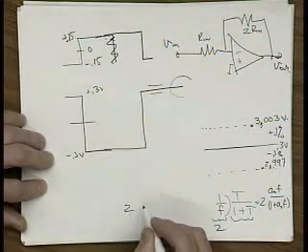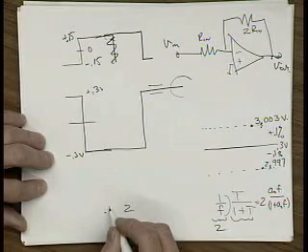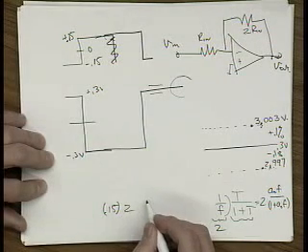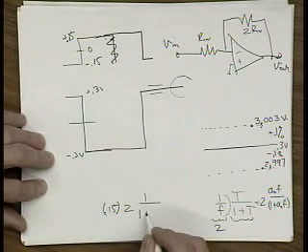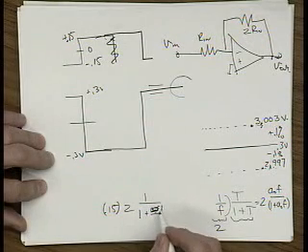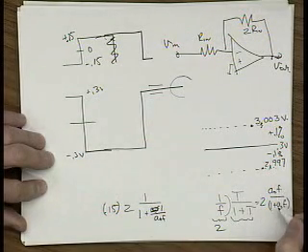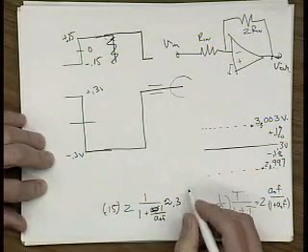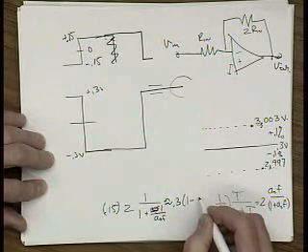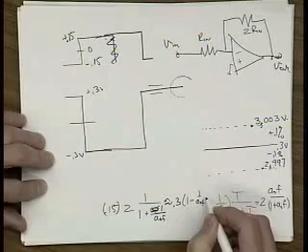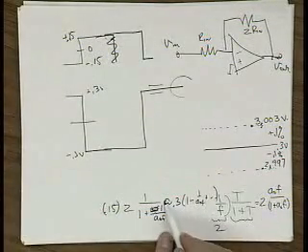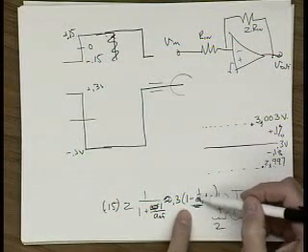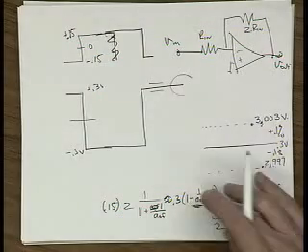And I can write that as 2, so my input signal is 0.15 volts, times 2 should be 0.3. Then I have this error. If I rewrite that as 1 plus A0F, or 1 over A0F, just divide top and bottom by A0F, this is approximately equal to 0.3 times 1 minus 1 over A0F, and so on, just the geometric series. So you can see this term, 1 over A0F, and these 1 over A0F squared terms and so on are probably pretty small compared to this term.